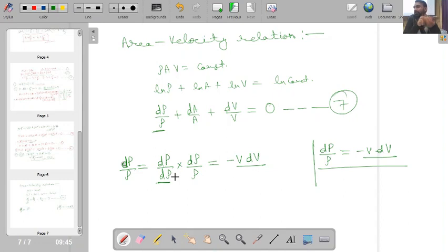So there is no diffusion of heat and no diffusion of momentum. This is a reversible situation, and for this flow we have not considered any additional heat addition or heat removal. So when I define this dp by d rho, I am defining it for an isentropic situation.